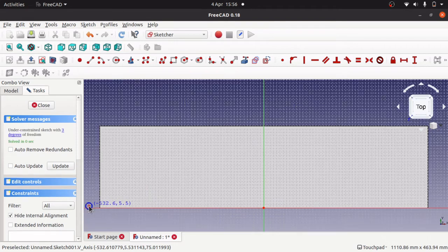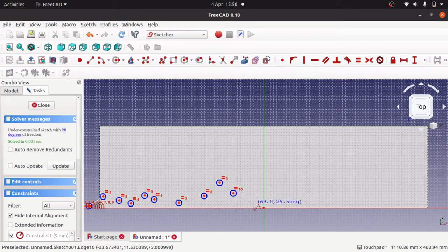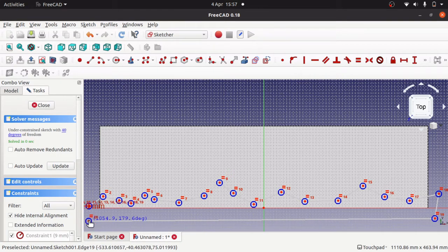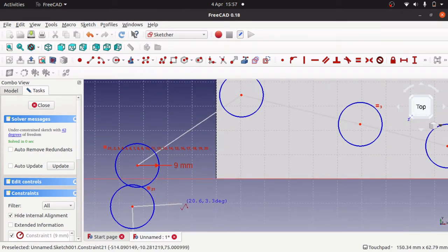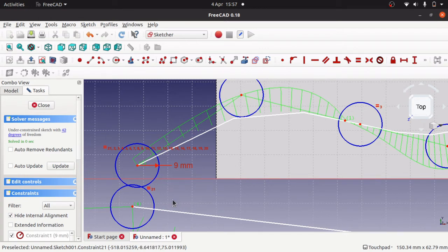So the first point is going to be outside, and I'm just going to make some kind of interesting pattern in here. You can make whatever you want, but this is just for demonstration purposes. And we'll come outside, come down, move right the way across, and then just going to put another point near the origin. We'll zoom in. I'm going to hit escape, get my mouse pointer back, hit escape again, there's my mouse pointer, and we'll just connect those two up. So our sketch is closed.